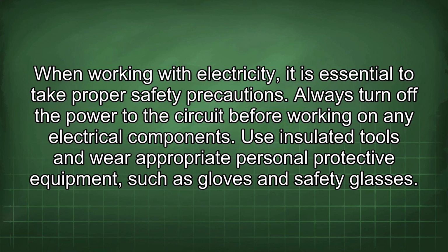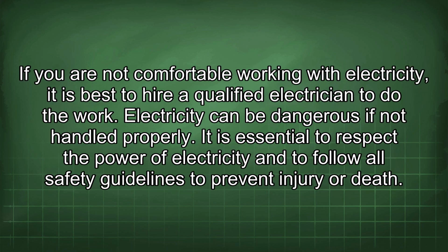When working with electricity, it is essential to take proper safety precautions. Always turn off the power to the circuit before working on any electrical components. Use insulated tools and wear appropriate personal protective equipment, such as gloves and safety glasses. If you are not comfortable working with electricity, it is best to hire a qualified electrician to do the work. Electricity can be dangerous if not handled properly. It is essential to respect the power of electricity and to follow all safety guidelines to prevent injury or death.